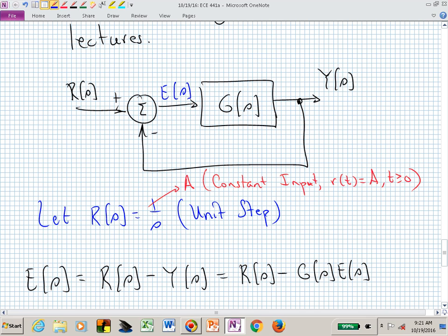We want to look at the closed loop transfer function's denominator polynomial and find those roots. You could do that with the Routh array and see if all of the roots are in the left half plane, or that you don't have any sign changes. And that would then allow you to conclude that your system is stable.